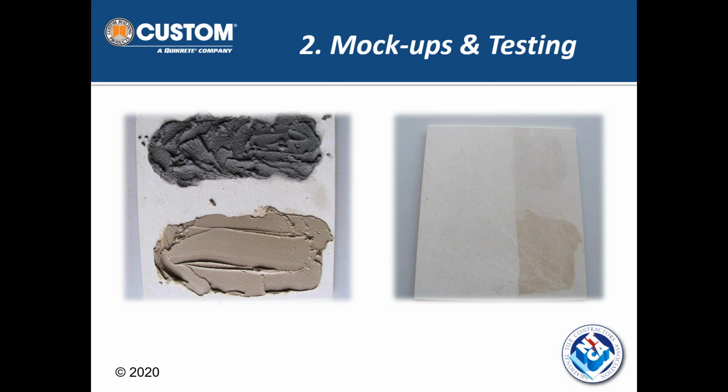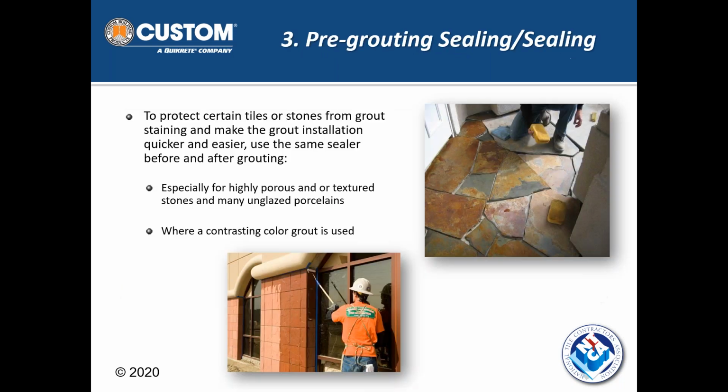The grout I let sit on there for the 15 to 20 minutes the manufacturer recommended, but when I came back and washed it off, that dirty wash water also stained the stone. So again, this is hard to avoid and becomes very costly and expensive if we don't calculate and factor it in.